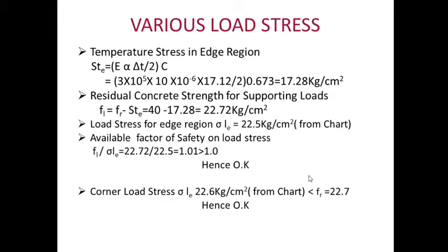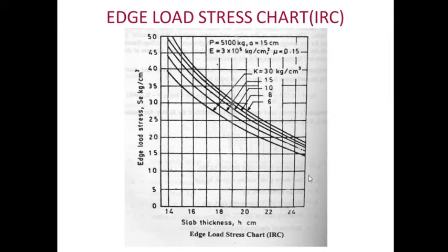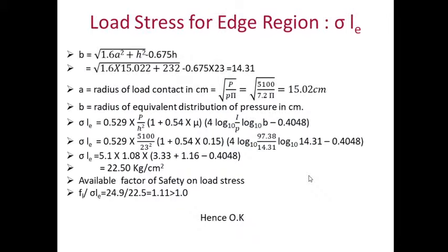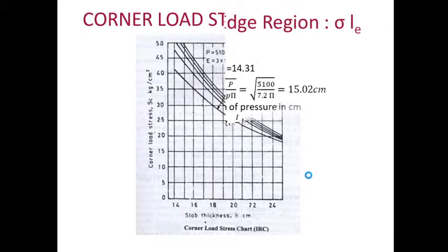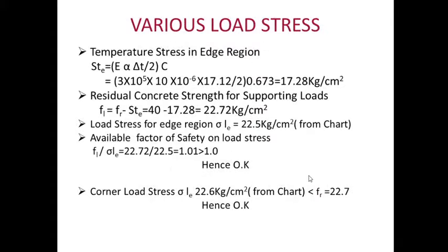This is the formula for load stress for the edge region. This is the formula for the interior load region, and for corner load stress, this is the formula for finding corner load stress. So the corner load stress and edge load stress can be determined by using the formula, or we can use the chart. So this is the chart which is used for finding the edge load stresses.